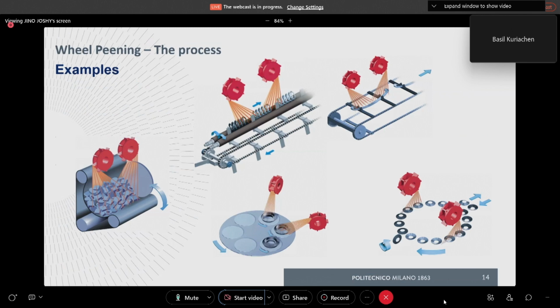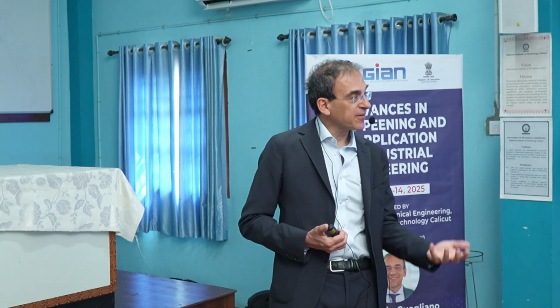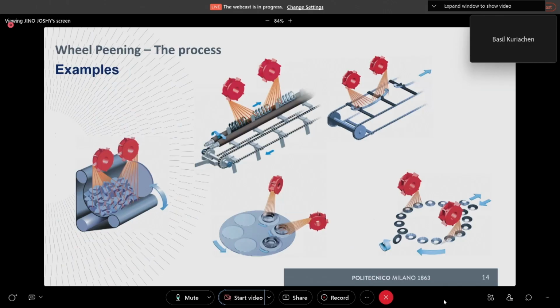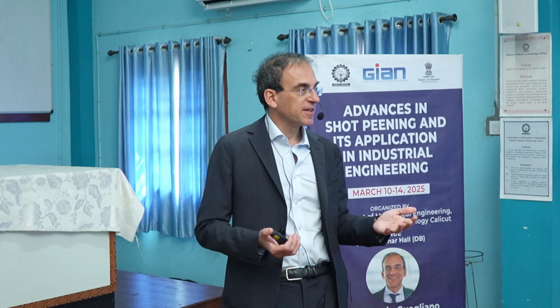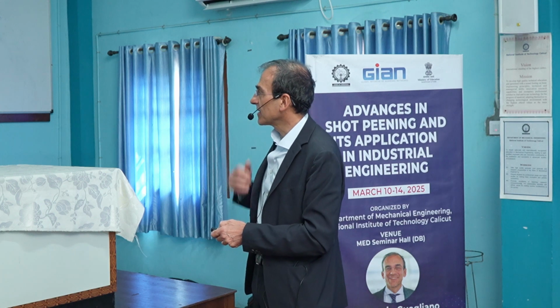And the same here, this is another kind of spring. This is a leaf spring, as you can see, and this is not stress peening. We are not applying a further load to increase the effect. It's just shot peening. Anyway, we can see here that by using an automated plant like this, making shot peening in a production line is possible and sustainable.